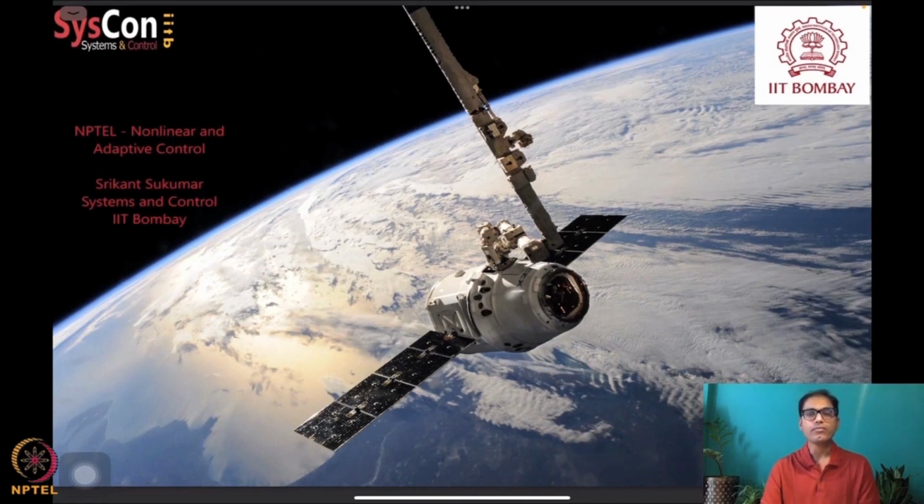Now, the point is that here we look at a generalization of the unmatched case, that is, when the uncertainty appears one integrator level above the control, and we want to look at vector states, vector controls, and vector unknown parameters. That's what we did in today's lecture and also the previous one. So we completed the proof. We started with the assumption that the first layer integrator has a nice adaptive controller along with a stabilizing Lyapunov candidate construction.